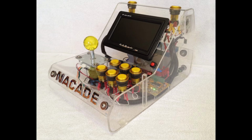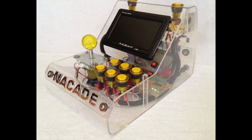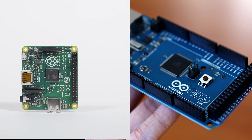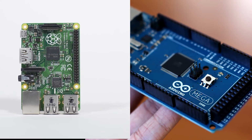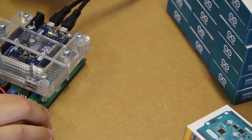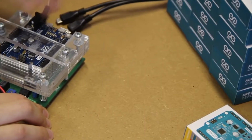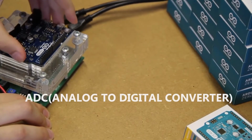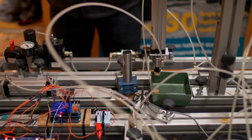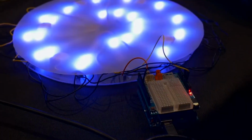When it comes to project development, the two most commonly used boards are Arduino and Raspberry Pi. So naturally, the next question that arises in our mind is, should we use Arduino or Raspberry Pi for our project? An Arduino is good at providing simple hardware solutions. For example, it has a built-in ADC and the Raspberry Pi doesn't. Many sensor modules use analog output, and using them with Arduino is way easier than with the Raspberry Pi.